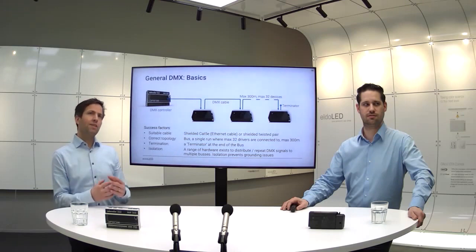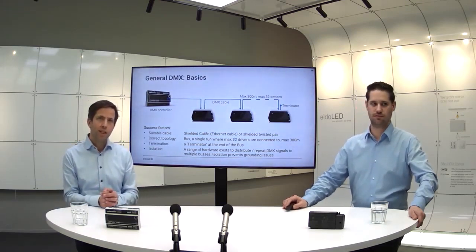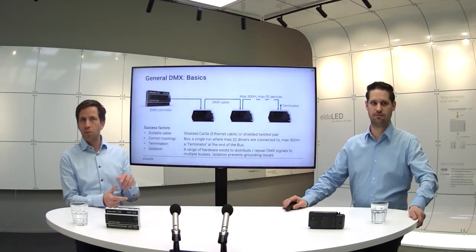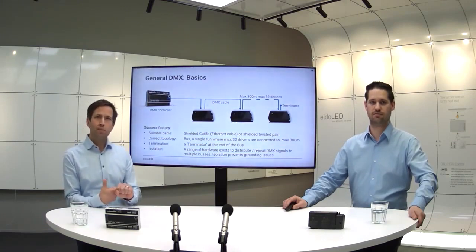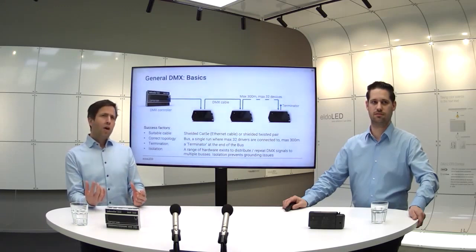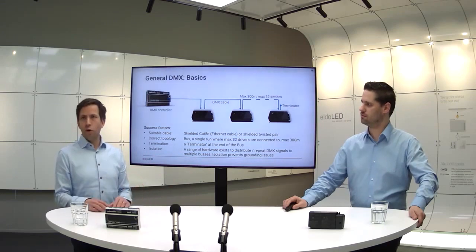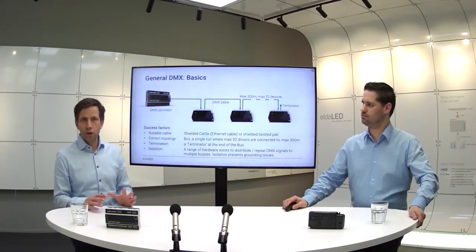Why is that important? DMX is pretty straightforward, but you need to keep a few success factors in mind. The first one is to use suitable cable, to use the correct topology, to terminate the line, and be sure you're dealing okay with isolation. When using quality equipment like eldoLED or Pharos, we've taken care of all the isolation for you, so you don't need to worry too much about that.